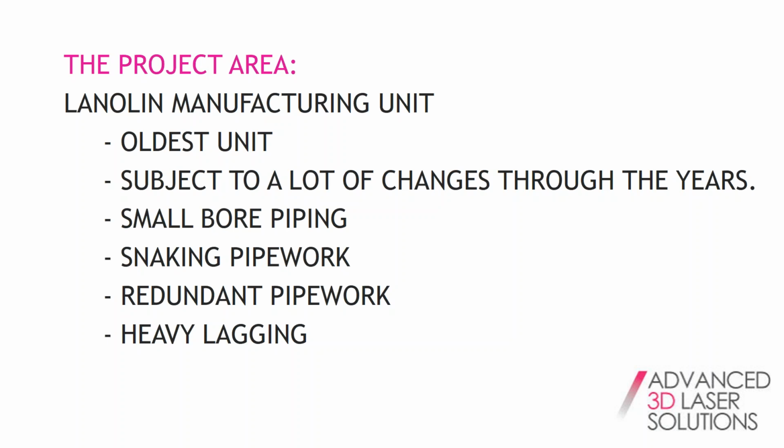You end up with this absolute snake pit of pipework, and it's almost impossible to trace. Because of how in-depth it was, there was a lot of redundant pipework, including heavy lagging, because a lot of the pipework had electrical or steam tracing in it to try and keep the product warm.